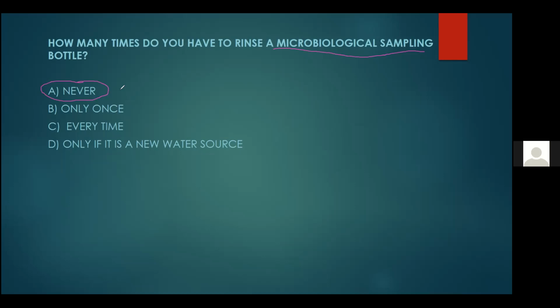Remember I said that you adjust your flow on your tap so it's very, very almost pencil-like. So there's not a lot of splashes. And basically you fill that bottle to the 100 ml mark, super important, but never, ever rinse it. If you rinse it, the sample's no good. You start again. Never rinse the bottle. Thanks, Dwayne. So never rinse that bottle, you guys. It's just a one-time thing. That's it.